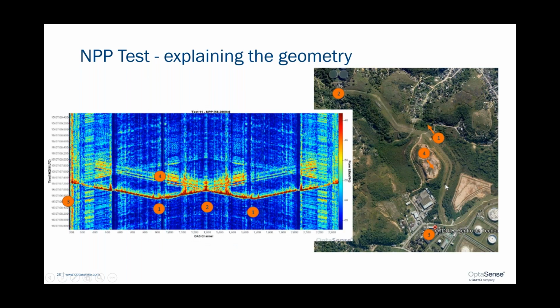So let's explain a little bit about the geometry then. So this is the same aerial view of the site, and I've numbered a few different points. We're going to look at the results from the negative pressure pulse. So can we detect an instantly failing burst disk from the negative pressure pulse that it creates? It's a slightly complex environment because the negative pressure pulses can travel many kilometers in a pipeline, and this one was, whilst suitable size for our needs, still only 2.5 kilometers long.